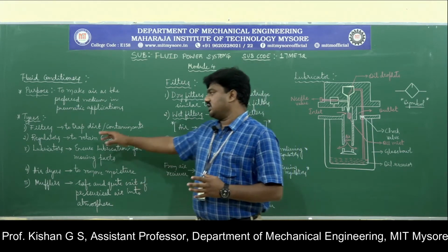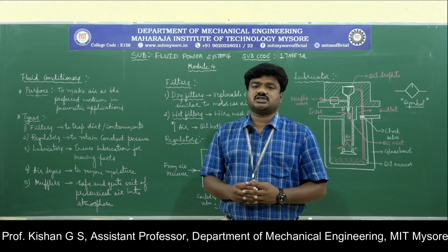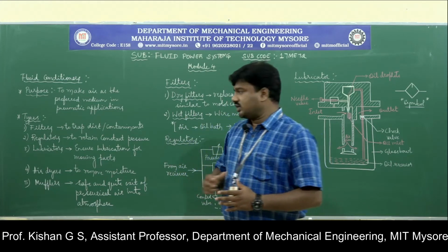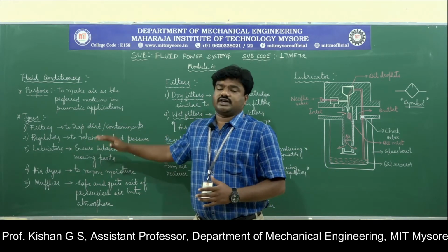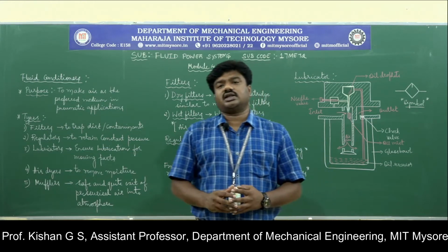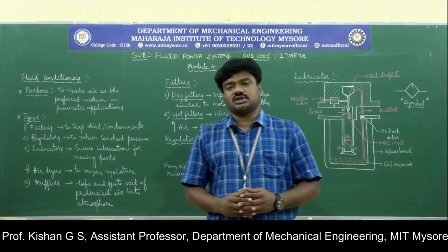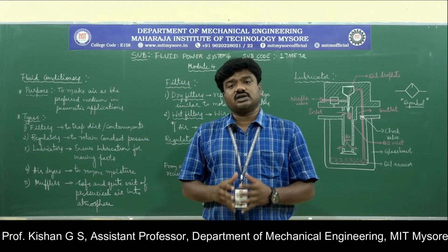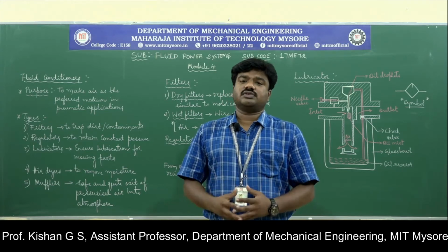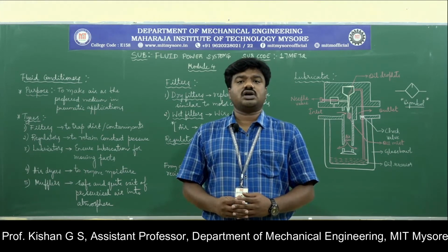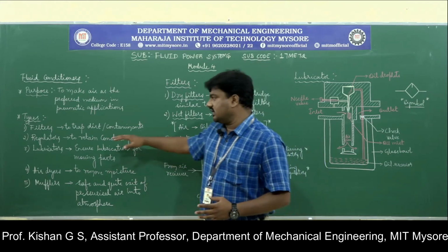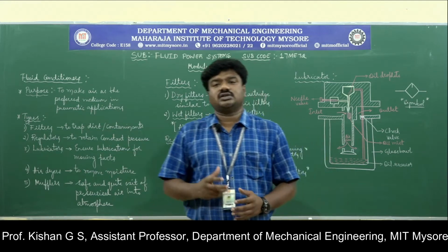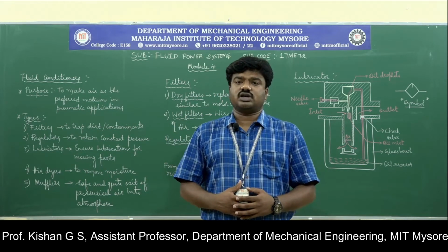Next comes the regulator. As the name suggests, a regulator is to regulate or moderate. Specifically, here it is the pressure regulator. Since we are targeting compressed air in the pneumatic system, the compressed air should possess a particular pressure only, which satisfies the performance of the work or the application. Hence the regulators are devices that retain a constant pressure in the air, which is the working medium.